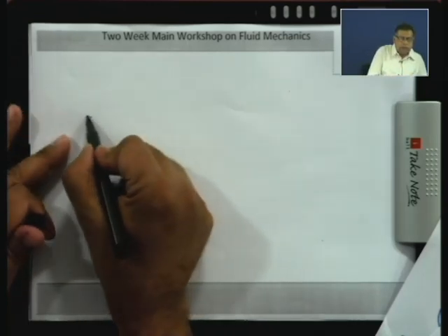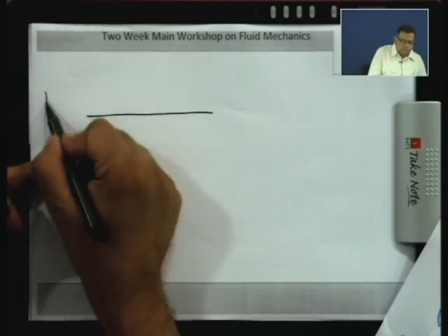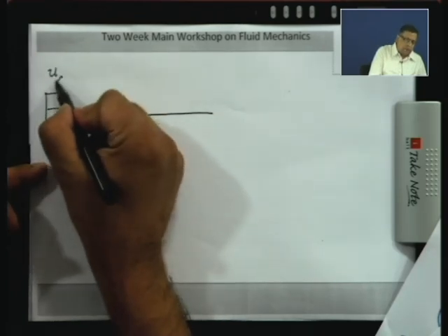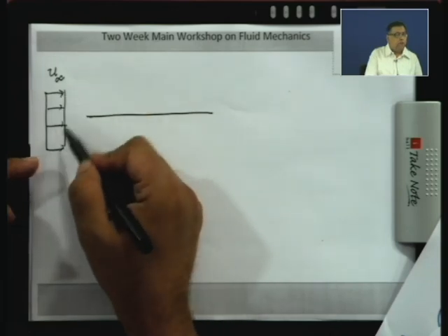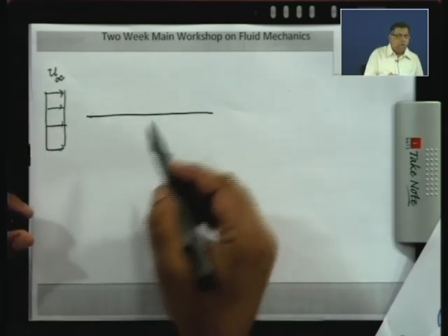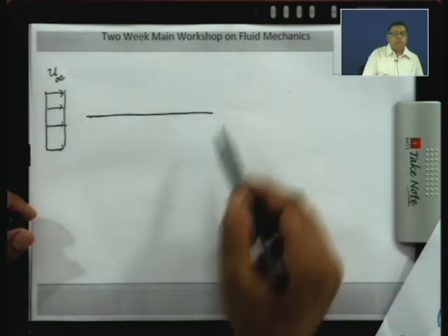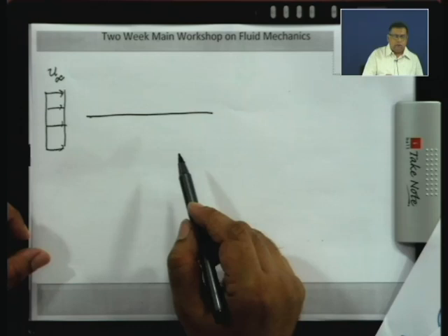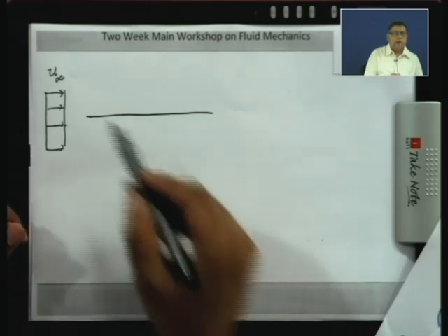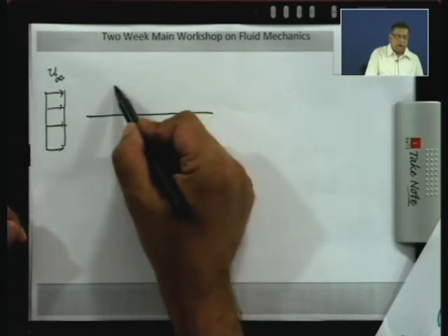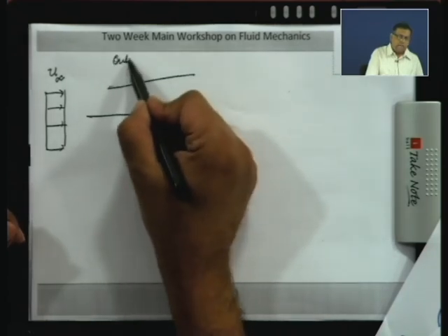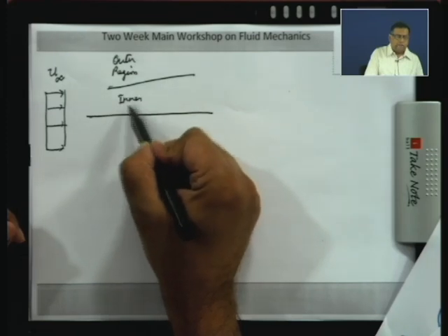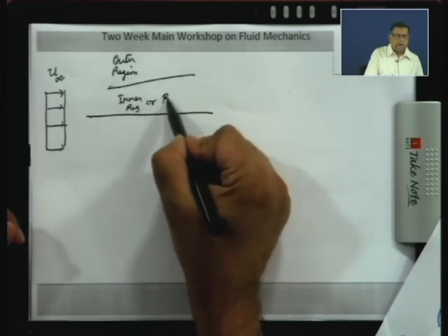So, we are looking in detail at the viscous flow past the flat plate. The upstream velocity profile is a uniform flow, the speed is u infinity. Now, the solution of the Navier-Stokes equations is difficult, you cannot get an analytical solution. So, what we are trying to do is following Prandtl's idea, we are dividing the flow field into two parts. We are calling one an outer region and you have an inner region. The inner region is referred to as the boundary layer.